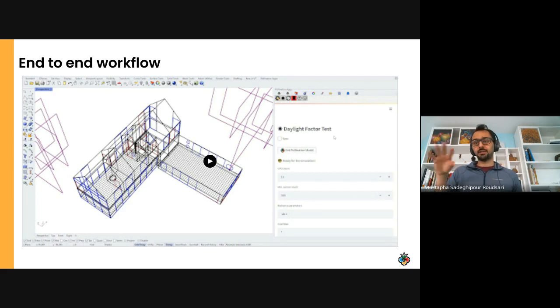This means now you can write apps, or in the near future you can write apps, and technically now you can write apps and start saying, keep track of average Daylight Factor in my model every hour, or on save, or trigger it. And then if it's going less than this, send me an email. Or if it's going that, give me a notification. So you can do all that.